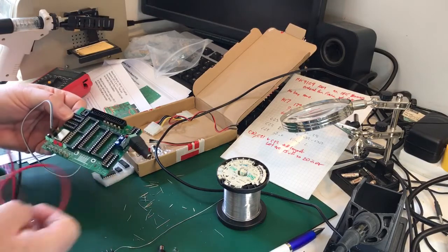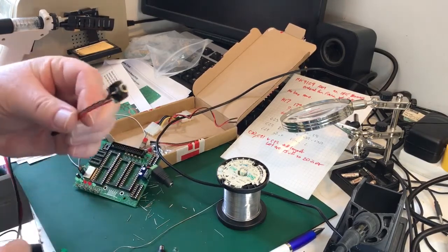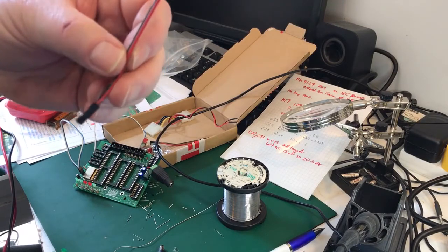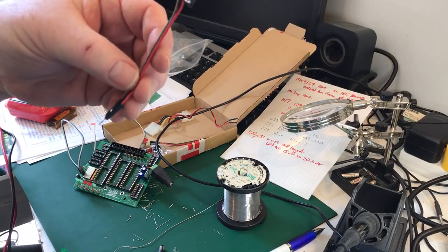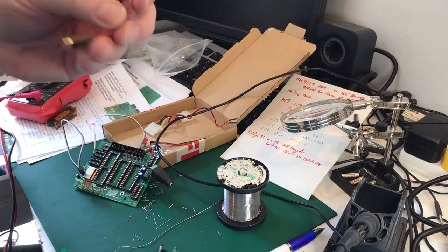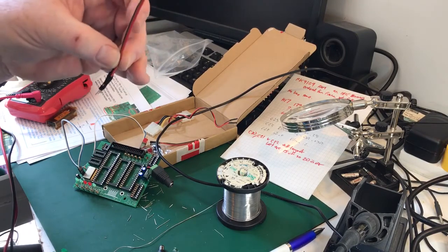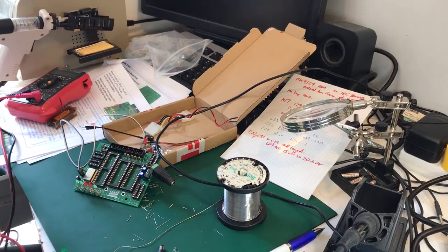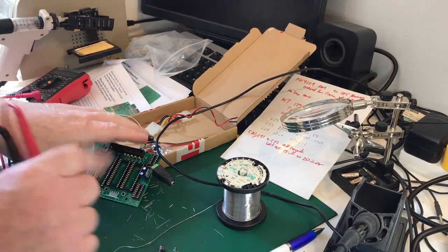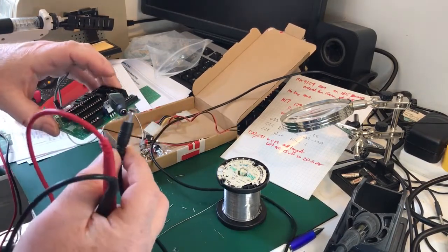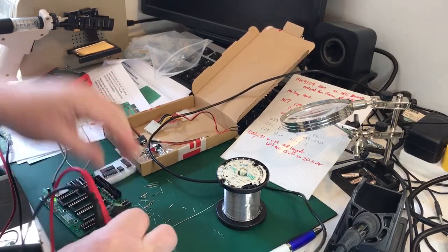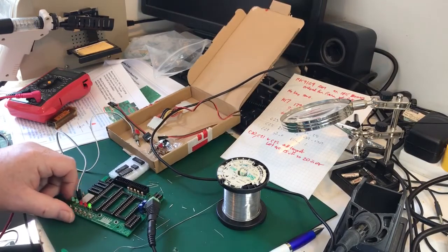And I've made up a little standard TTL 5 volt connector. I didn't usually use blue for the RX, but I didn't have that, but I think red is TX, so it's still good to go. Basically now if I power it up off a sort of 9 volt supply, we should have a 5 volt rail on the chips, and we got a little green light, which is good.